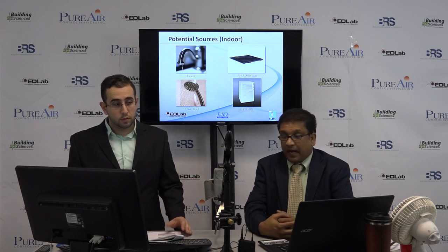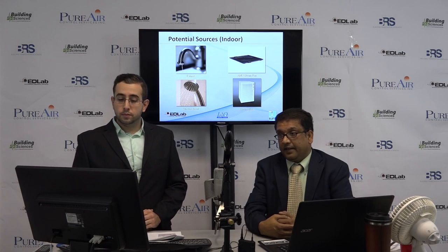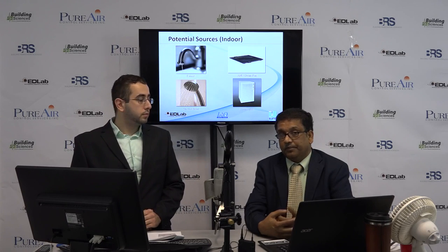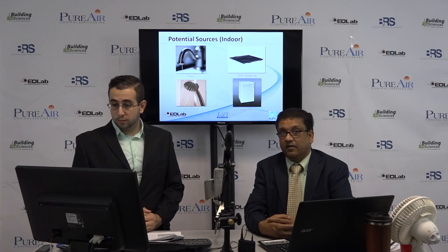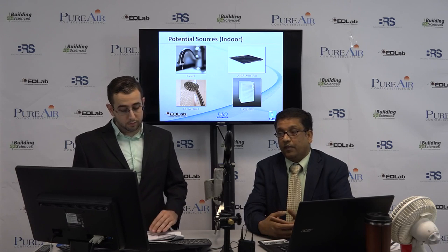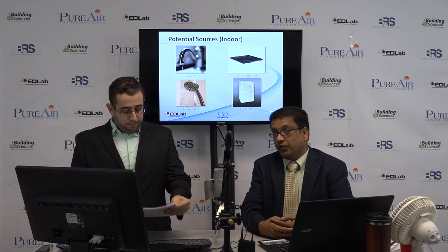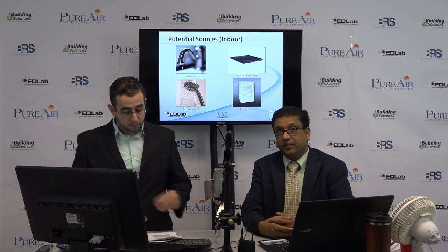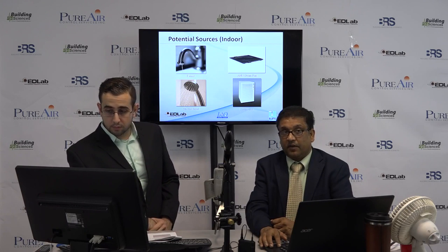Now, I wanted to give you a photographic idea of how you can narrow down the source. For example, the water faucet, which is very common in a dwelling place or in an industrial or residential setup, is one of the main places where biofilm can be formed, such as shower head, AHU, drain pan, humidifier, etc. Those are really the places to look for, where the Legionella can flourish.